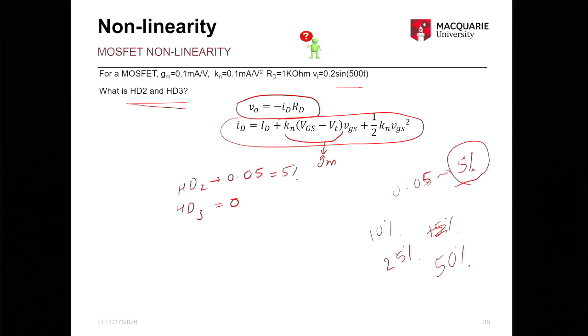It is called a ferrite bead. It's an iron core with a few coils wound on top. So it works like an RLC circuit, right? Your wire is like a conductor, and this one has this coil and a small resistance to it. So it's like an RL circuit. An RL circuit can be used as a high pass or a low pass filter. So this is a low pass filter, which attenuates all the high frequencies.